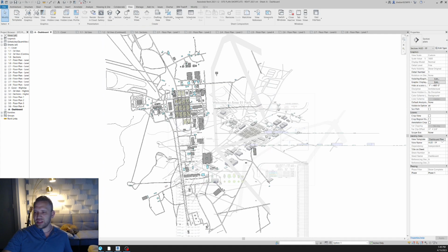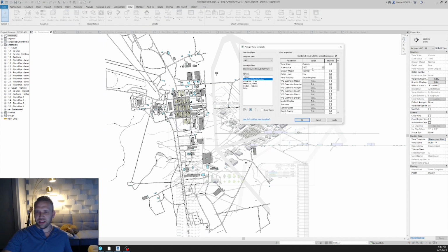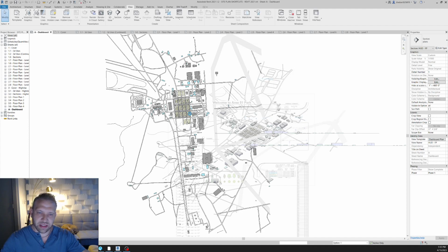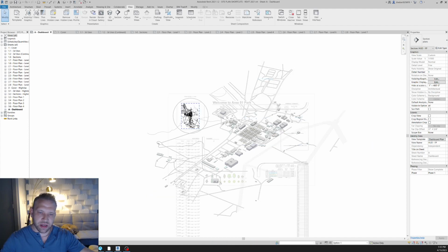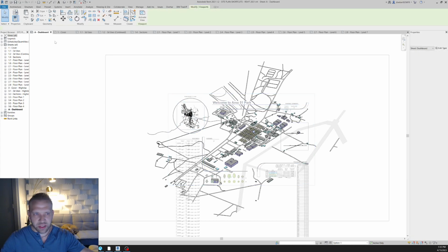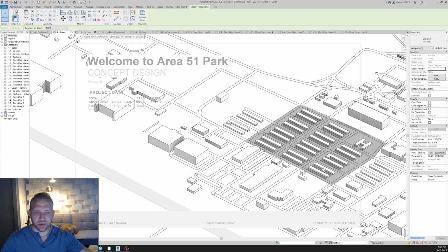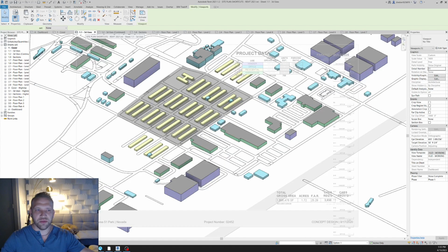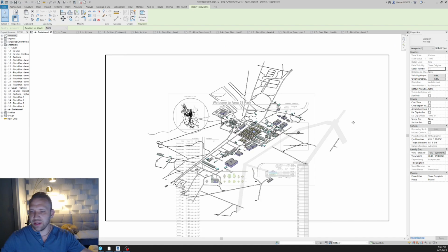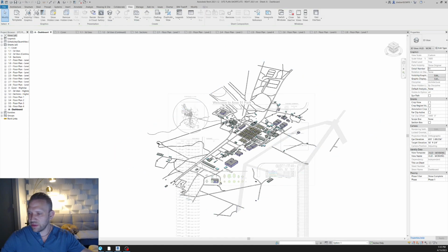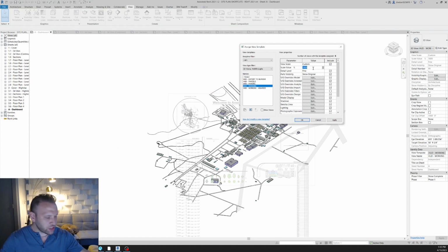What I'm going to do is, on this sheet, change the scale of these two views here, and you'll see what happens when I do this. We basically need to scale this so that it fits inside of this box, and that's going to scale our plan. You can actually see, if we go to these other sheets, that our views are way off. Like the scale of this view is way off. So I'm going to change these views; they should match in scale.